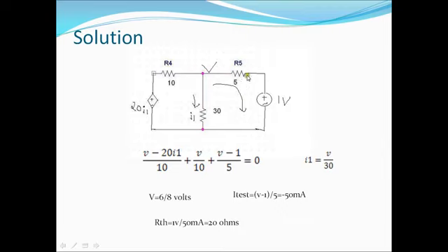So we need to introduce a voltage source as a test source or a current source depending upon the situation. Here we have 5 ohm, so we need to introduce a voltage source such that we get current. If we have just a short circuit here, that is just a line, then we can introduce a current source.